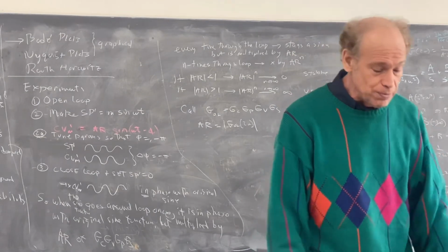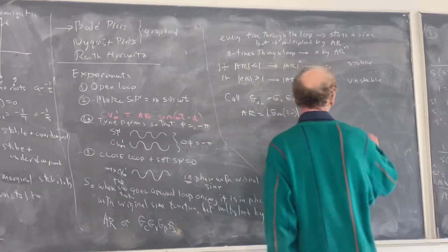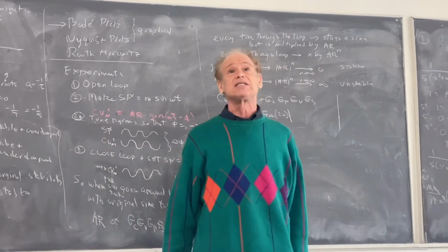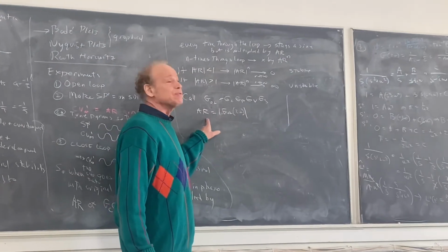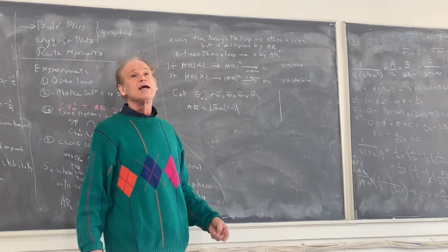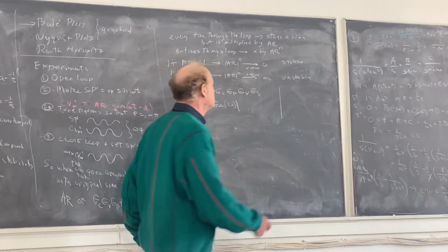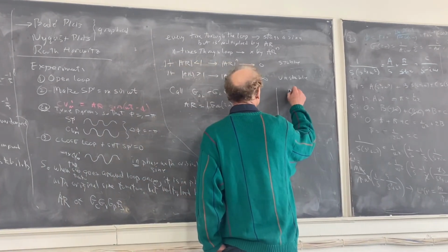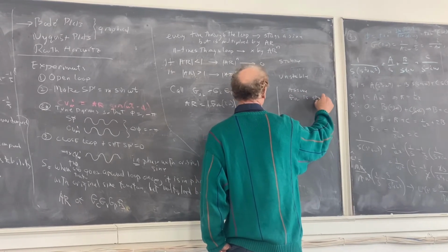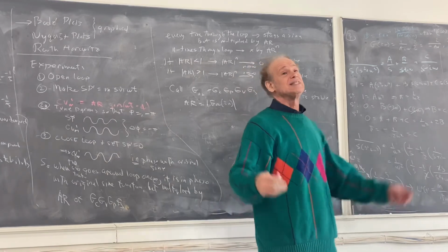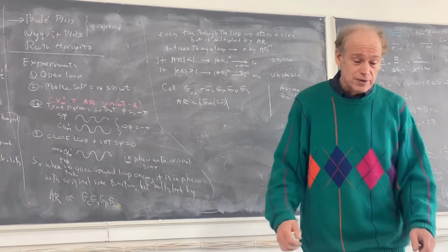Now, what are we assuming here? In order for this to make any sense, for it not to be obviously unstable: if G open loop itself is unstable, if the amplitude ratio is infinity, then the system is unstable. So to even bother with this, we assume that GOL is stable. Because if it's not stable, then we don't even have to do this. It's clearly unstable.